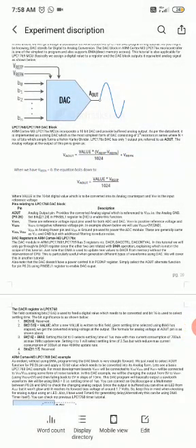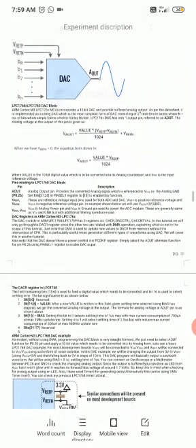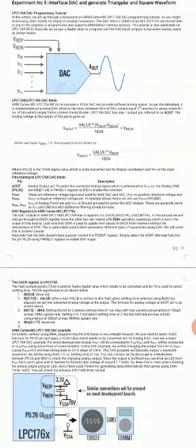So how to program this DAC? There are a number of registers inside this DAC, and we have to change those registers to get this analog signal. Where is this AOUT pin connected? The AOUT pin is connected to P0.26.